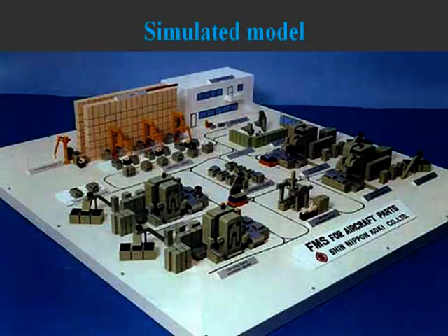placing all the machines, placing all your conveyors, robots, etc. Give the processing times for these machines, processing rates and other things, and you can run the simulation model and you get what could be the output and performance measures of this. There are several languages available to create simulated models and test the FMS performance. They're all called discrete event simulation models.